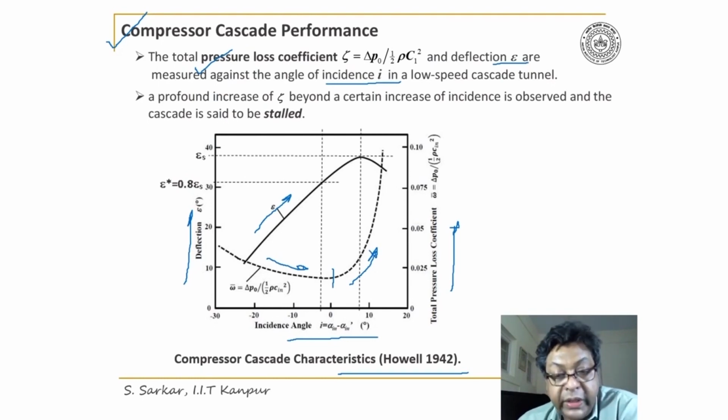Now look, even if we go beyond the minimum pressure loss, the deflection tends to increase, but at a certain point it becomes maximum, then tends to decrease. Where it becomes maximum, that's called the stall condition.